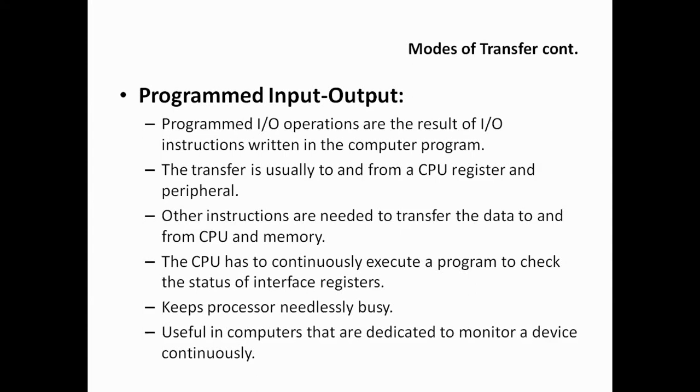You have to continuously run that program, and after that there will be a transmission that may be of 10 milliseconds. So it may happen that you have to run the program for 100 milliseconds, then data will come for only 10 milliseconds. So obviously it keeps the processor busy, needlessly busy.